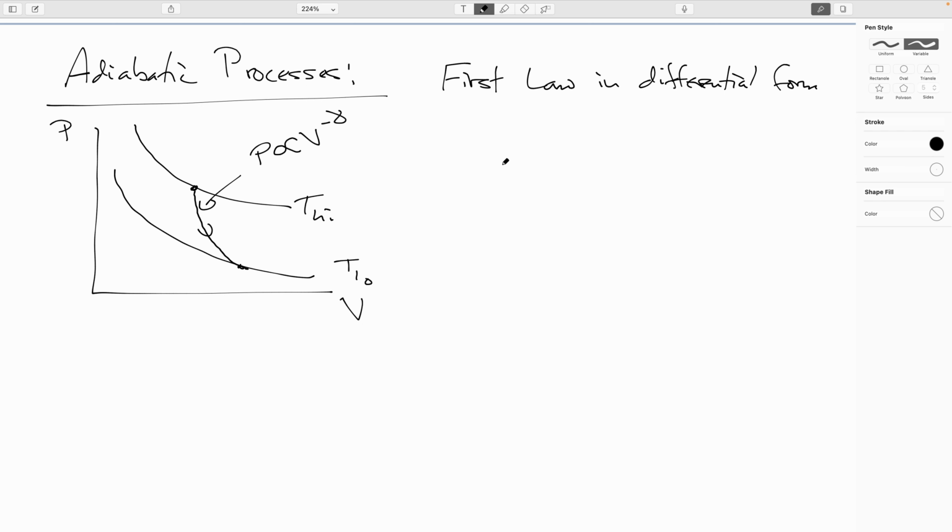So taking the first law and differentiating it, you would say the differential of E thermal, dE thermal, would equal the differential of the work, dW. Now here's the bit where I have to finagle for a sec. You'll notice that for the heat bit, I had to put a little bar through the Q. And this is because, remember, heat is thermal energy in transit.